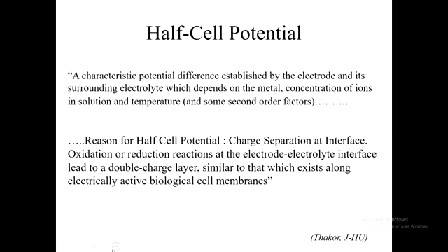Now, one of the things that we do have to deal with from a practical point of view with real electrodes is the half cell potential, and that is why specifically the silver chloride electrodes that we've used in the labs here are particularly favoured, because as well as being stable, they have a very reasonable half cell potential, 0.3 of a volt roughly. So that's quite useful for us.